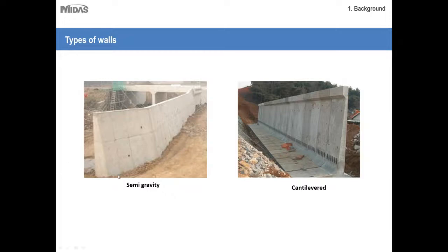But this additional sloping surface behind the main wall gives the structure additional stiffness and strength against overturning, and it makes it more stable. Again, it has a combination. It could either have a core filled with gravel or filled with concrete, or it can also be constructed as a monolithic set, something like a buttress wall.